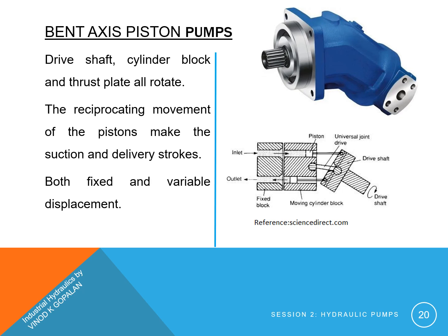Drive shaft, cylinder block, and thrust plate all rotate. The reciprocating movement of the pistons makes the suction and delivery strokes. They are also available in both fixed as well as variable displacement models.